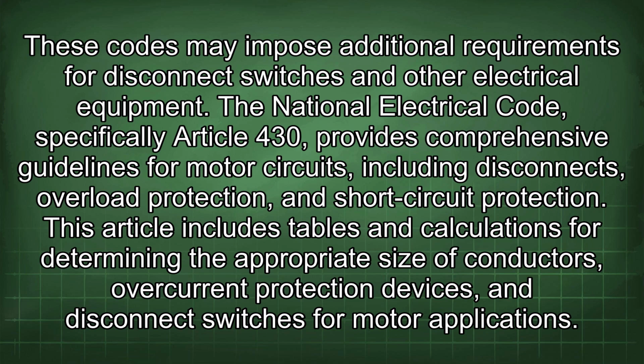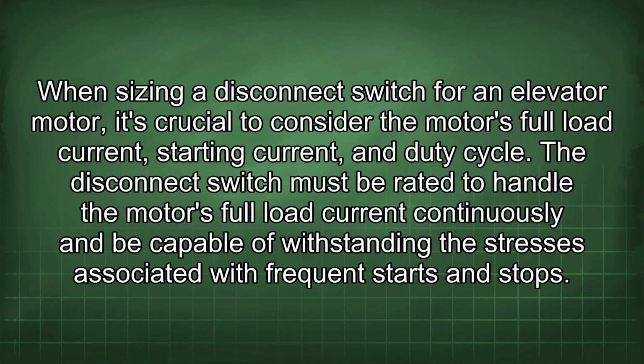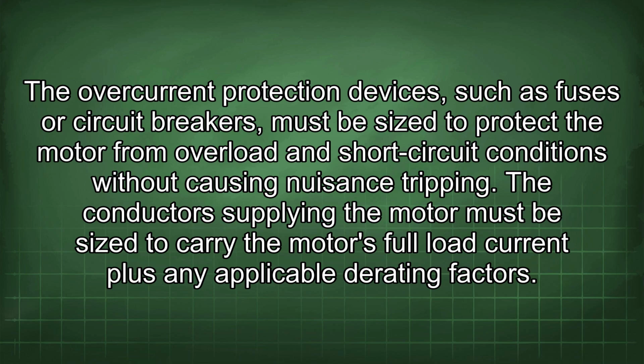When sizing a disconnect switch for an elevator motor, it's crucial to consider the motor's full load current, starting current, and duty cycle. The disconnect switch must be rated to handle the motor's full load current continuously and be capable of withstanding the stresses associated with frequent starts and stops. The overcurrent protection devices, such as fuses or circuit breakers, must be sized to protect the motor from overload and short-circuit conditions without causing nuisance tripping. The conductors supplying the motor must be sized to carry the motor's full load current plus any applicable derating factors.